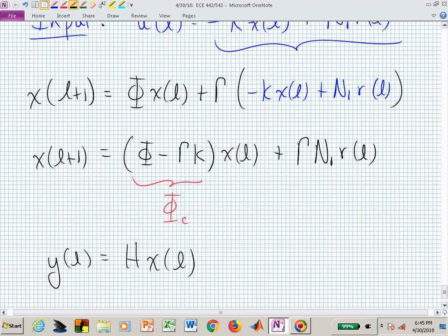If we say go to 10 and it actually goes to 10, what have we talked about before when we said, if we put in a constant and we get out that same constant, what particular aspect of our system were we dealing with? We were worrying about the error, and what gave us zero steady state error due to a constant? We needed a DC gain of 1.